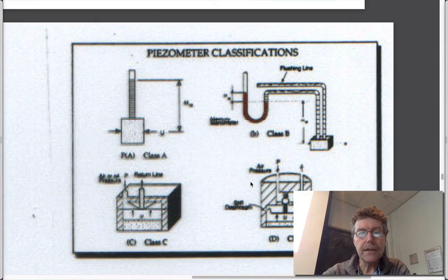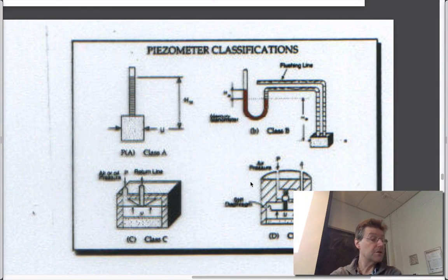And ultimately, in these wellbores, once you're finished with it, you might want to be able to measure pressures, as in a standpipe piezometer. You might be interested to measure permeabilities through well tests, Lugeon tests or slug tests. And you might be interested to take water quality samples as well, all in these completed regions.